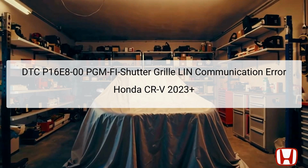The shutter grille plays a crucial role in optimizing airflow for engine cooling and fuel efficiency. If the shutter grille is not functioning correctly, it can lead to performance issues. The components involved in this error primarily include the shutter grille, the PCM, the DC-DC converter, and the 12-volt battery sensor. The shutter grille's location is often at the front of the vehicle, while the PCM is usually found in the cabin, hidden under the dashboard. Understanding these locations and components will help pinpoint the issue effectively.